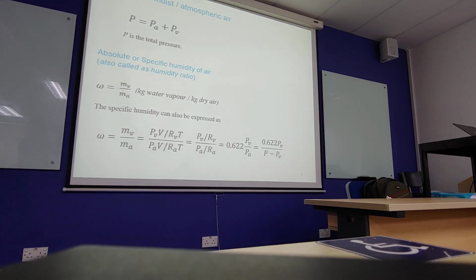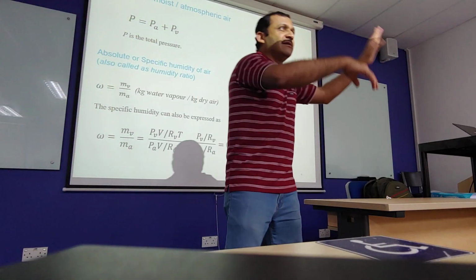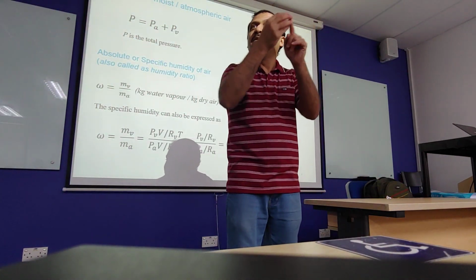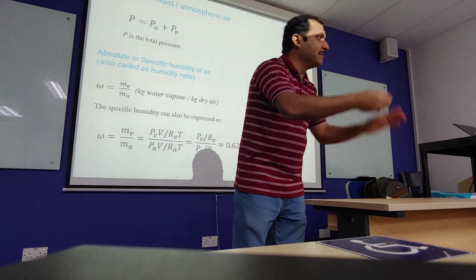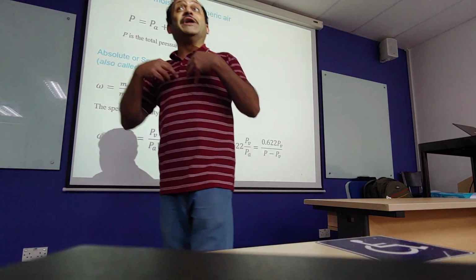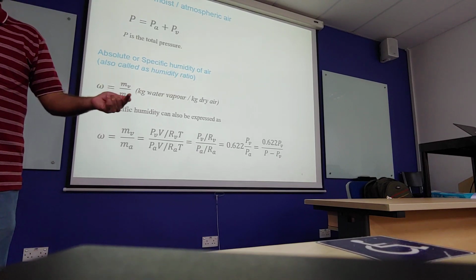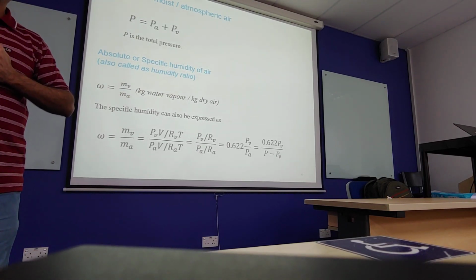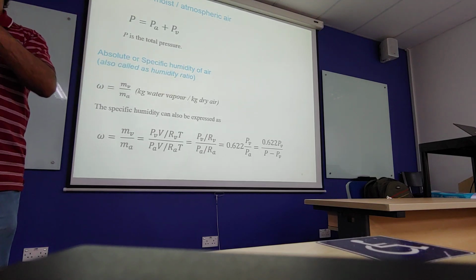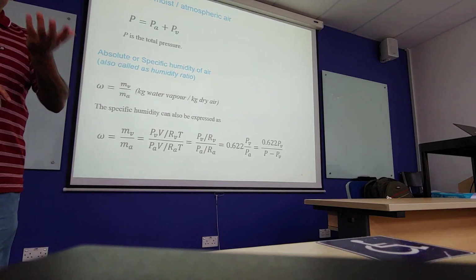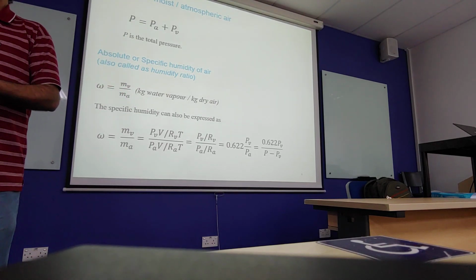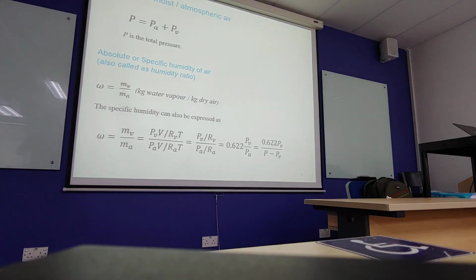So get two identical thermometers, one without anything, just dry, empty, and one with a small piece of wet cloth on it at the tip. Now tell me, based on your intuition, based on your experience, which one of those would read higher temperature relative to the other one? Without the wick, without the wet cloth, or with the wet cloth? Dry. Dry will read higher temperature. Wet will most likely read lower temperature because it's wet, it's going to cool down, and that's exactly what it does. And that's exactly what we want it to do, because then it helps us to estimate.